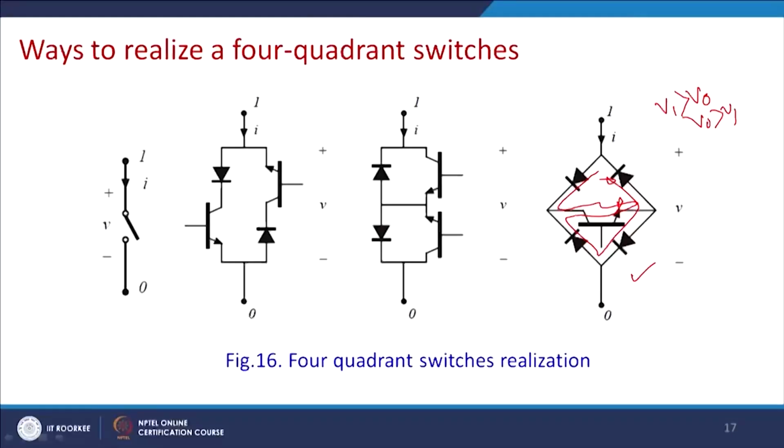But the disadvantage is that it will have losses, it has to incorporate the losses of the 3 devices, because all it has is blocking voltages, and generally power diode voltage is more than 1 volt. So, we will have almost a 3 volt drop across these devices. Now, this is one of the realizations with fewer control switches.